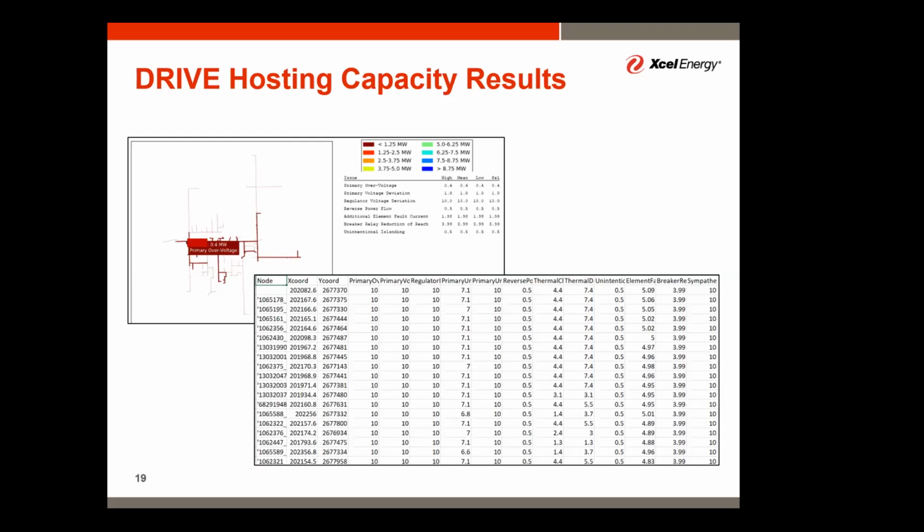We're not taking the substation information, and it does an actual analysis. Something like a pre-app report doesn't really tell you voltage violations; it's more of a high level capacity. Even at that, it doesn't always show you the total amount of capacity, because there could be limitations further on the feeder. But the hosting capacity would give you better information from a voltage standpoint, if you're seeing potential issues there that you couldn't get from a pre-app report, if that helps.